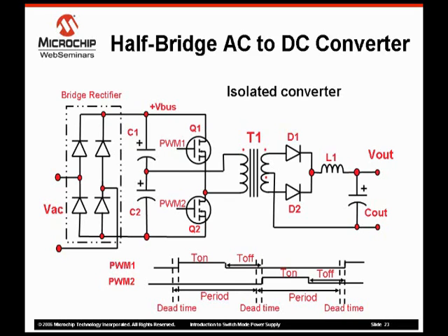There are two power pulses transferred each cycle, enabling the use of a smaller inductor and capacitor. The flux hysteresis loop operates in quadrants 1 and 3, so the core utilization is high, allowing the use of a smaller core. The input to output voltage transfer function is proportional to the input voltage, duty cycle, and the transformer turns ratio. Flux imbalance is not an issue with a half-bridge converter because one winding of the transformer is connected to the supply capacitors C1 and C2.